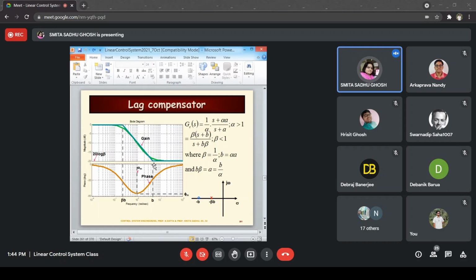It goes down at a minus 20 dB per decade slope, that is the asymptotic magnitude plot. And then from the next corner frequency, we have the zero coming in. That zero means a plus 20 dB per decade, which is added to the minus 20 dB per decade, and finally you get a constant value over there. So basically, this is the asymptotic magnitude Bode plot.